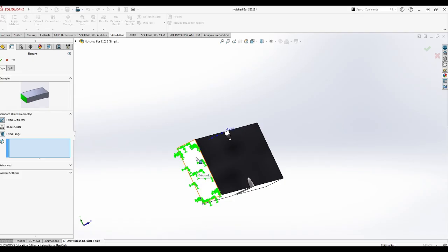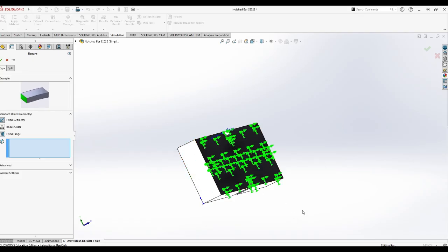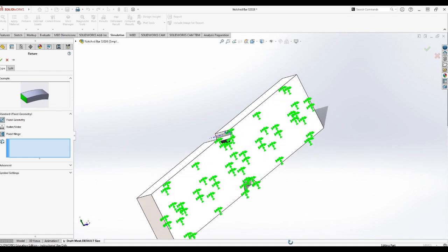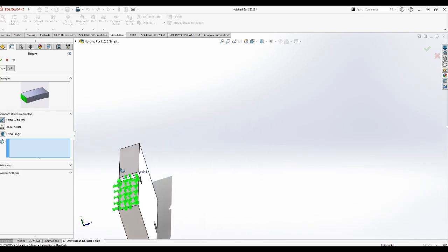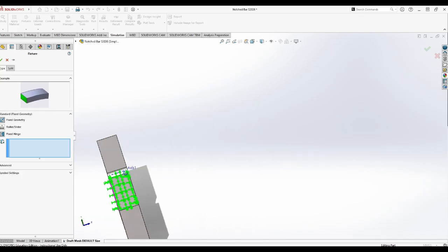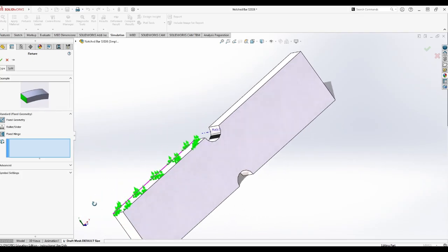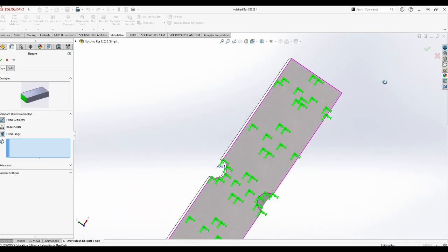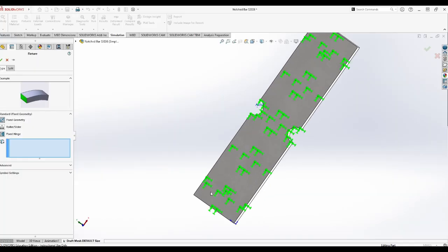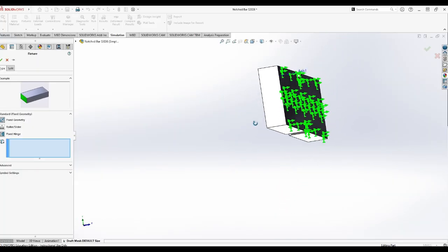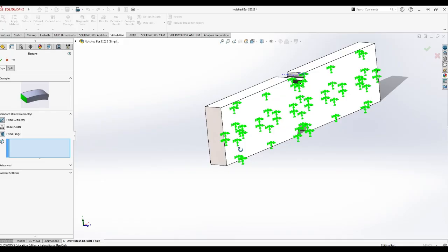They are the same, but because one will be positive x and the other will be negative x, it's better to fix the face which is at 0 right now. But again, the result interpretation can be slightly different depending on how you fix it, but otherwise the part is going to be fixed, and it can be fixed from either end. In my case I'm fixing it where the origin is.